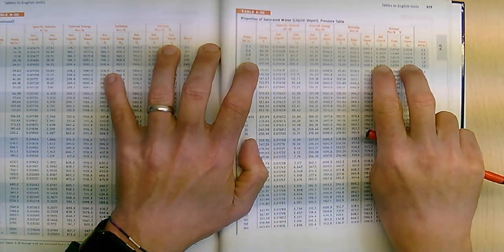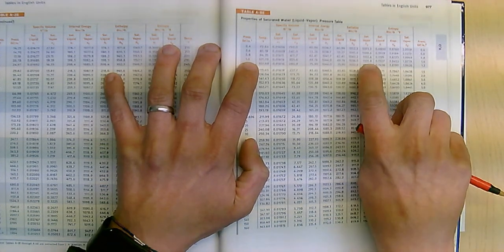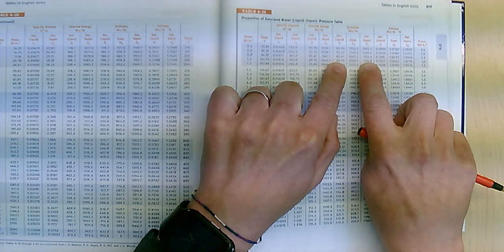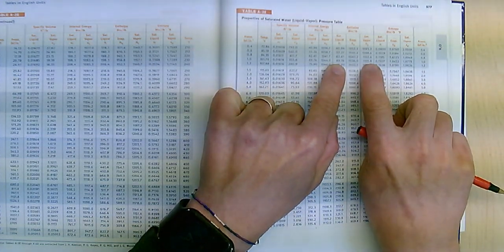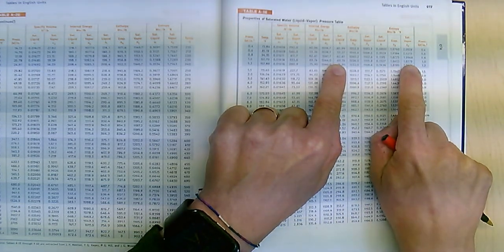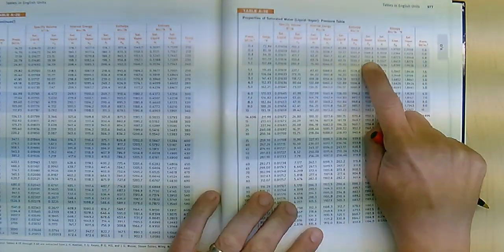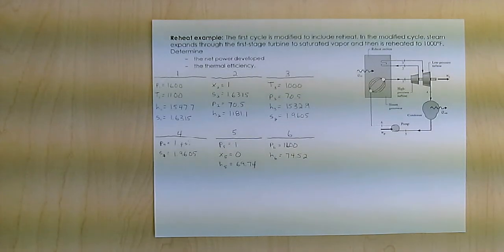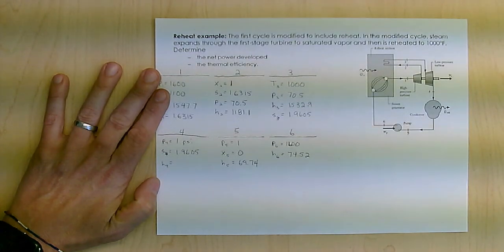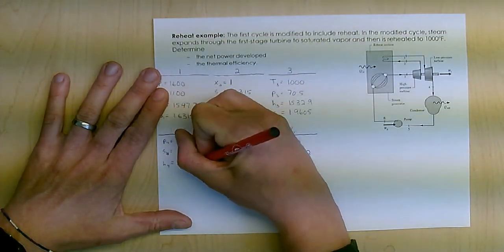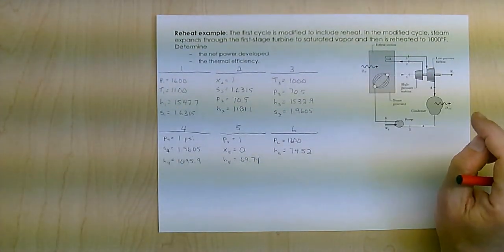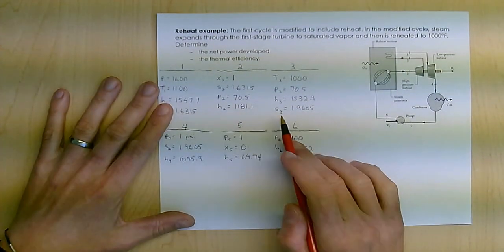So I'm going to have a very, very high quality, and that enthalpy will work out to be 1095 when I do the interpolation. Again, very close to the 1105 that is saturated vapor at 1 psi. I'm just below that because I'm just below the 1.97 at 1.96. So I actually get 1095.9, and that sets my state. I set that because I know P and S; any two properties set my state. So it's the same process using isentropic and constant pressure processes to figure that out.